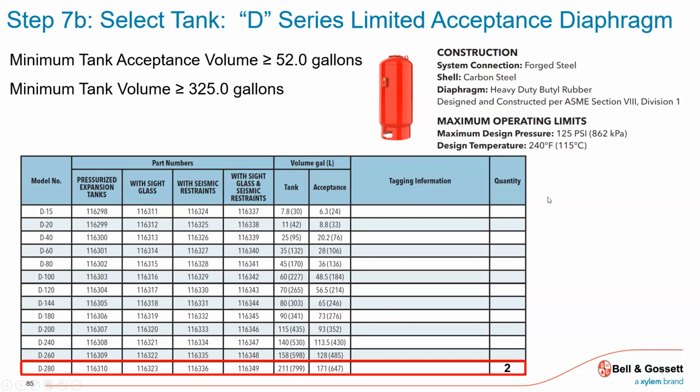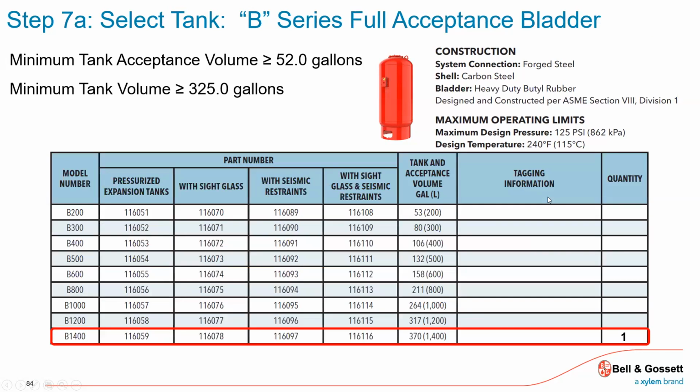So two of these diaphragm style tanks or one of these larger bladder style tanks to meet the overall requirement, because there's two conditions: volume of water, what am I heating it to? Fill pressure, relief valve. Those two factors I have to meet.